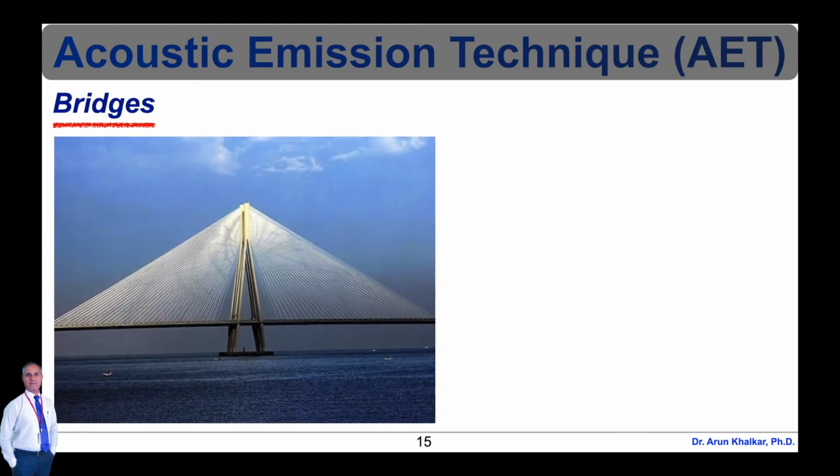Bridges contain many welds, joints, and connections, and a combination of load and environmental factors heavily influence damage mechanisms such as fatigue, cracking, and metal thinning due to corrosion. Bridges receive a visual inspection about every 2 years, and when damage is detected, the bridge is either shut down, its weight capacity is lowered, or it is singled out for more frequent monitoring.